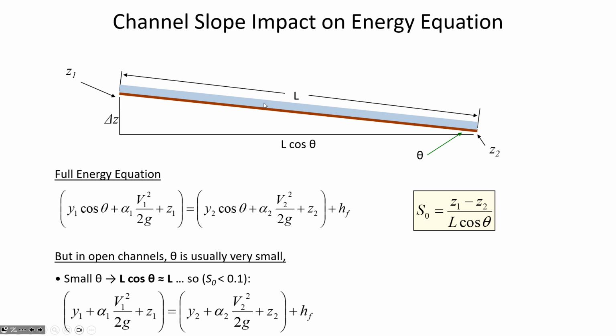And so when I say the distance between 2 points, that would be a top view distance, but we'll also assume that that is the actual distance that the water is flowing over, even though there is some delta z. So what I'm saying is let's neglect the difference in length between the inclined section and the horizontal section.